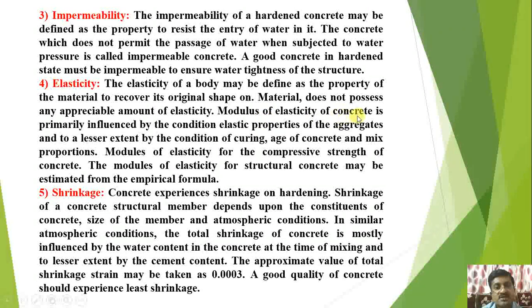Modulus of elasticity of a concrete is primarily influenced by the elastic properties of aggregates and to a lesser extent by the condition of curing, age of concrete and mix proportion. Modulus of elasticity for compressive strength of a structural concrete may be estimated by the empirical formulae.